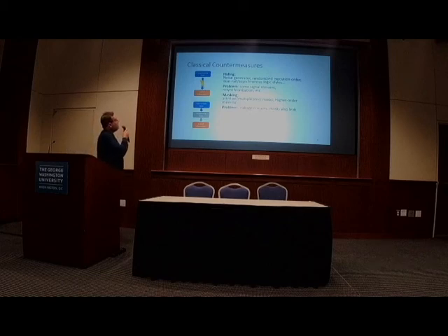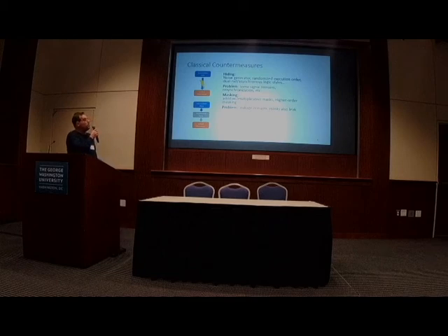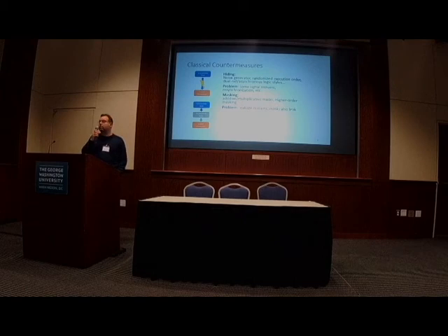Masking is the other classical countermeasure, and it is very effective. Basically, you hide your data by adding random masks throughout the computation path. There are different types of masking; you can do higher-order masking as well. The problem is that leakage still remains. Masks also leak at times, so it's not foolproof, but it's another standard mitigation technique.